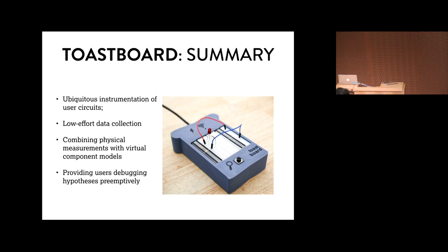Yes? Have you thought about basically trying to pull simplified models from SPICE rather than having to have this transfer of experts looking at the data sheet coming up with a transfer function, because those IO models already exist. Yep. Excellent. This is clearly something we haven't gotten around to, but it's already come up multiple times, that really leveraging all of the work that's gone into SPICE, into simulation tools, and into device characterization, right? We should leverage that here. Because you don't need to do full-time domain nodal analysis where you're looking at frequency response, but you're just looking at steady state. Yep. And that's computationally very easy to do. So yeah, that could fit in. Yeah, I fully agree.